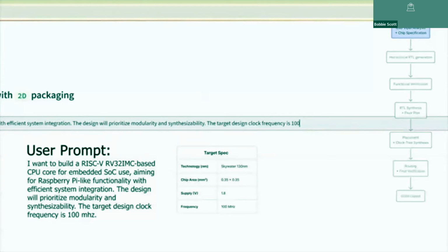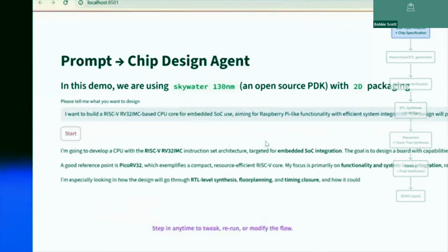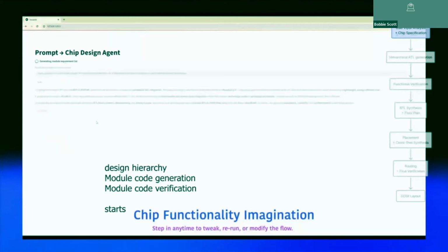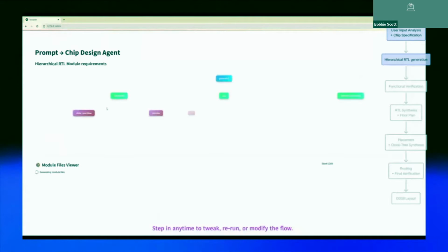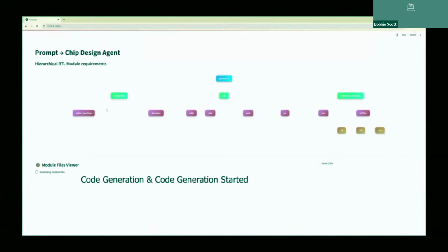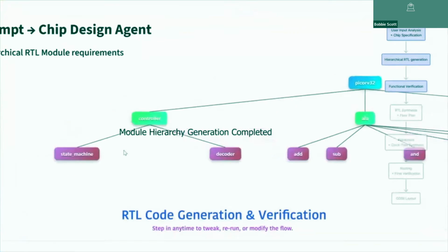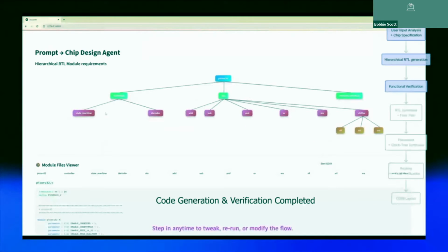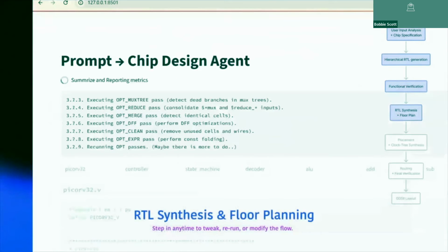for a non-expert user prompt given in NLP, how do we convert this into a chip design and layout? Then there will be a bunch of intermediate results. So we actually use the large language model agent to automate every single step, starting from a prompt. Then we build this parser that builds all these hardware modules. And based on these different hardware modules, controller, multiplexer, multiplier or adder, we just generate the code and then we do a verification, we debug this. And after that, we enter into the physical design.